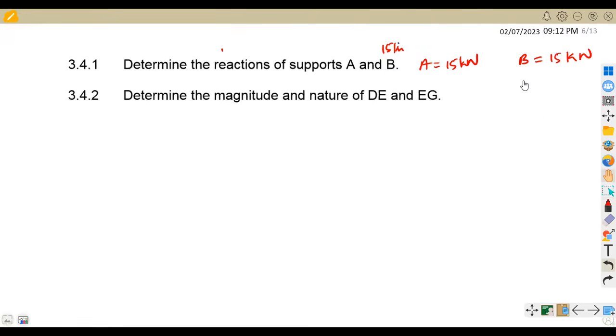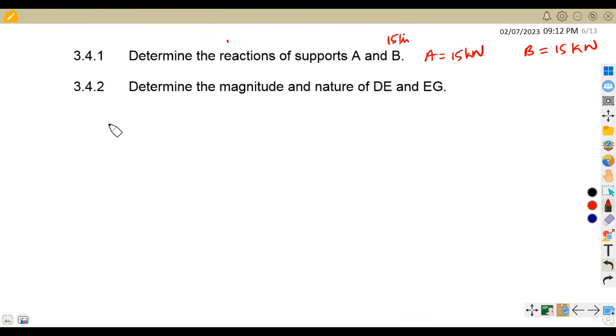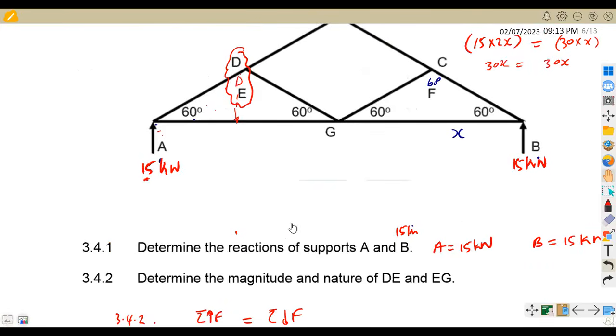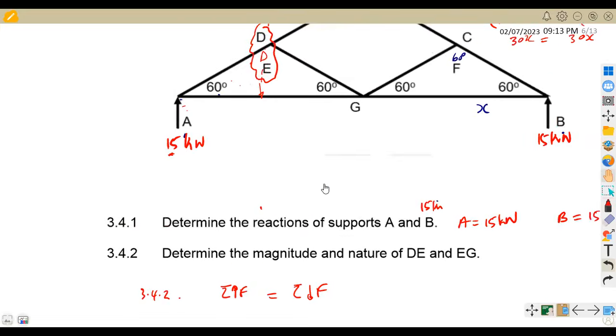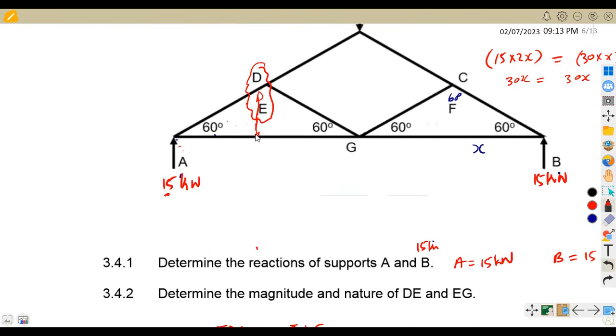The vertical components represent the forces that are going up and the forces that are going down. We know that the sum of the upward forces must be equal to the sum of the downward forces. Up, we have the 15 kilonewton force, which is facing up, so that's 15. The one facing down is the one on top here, which is DE. But remember, every force is supposed to be affected by an angle. If there's an angle like this, it's DE sine.